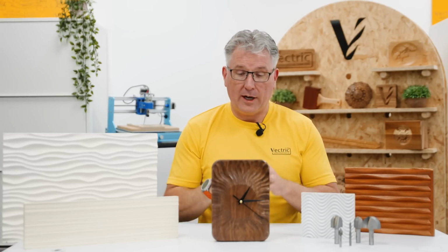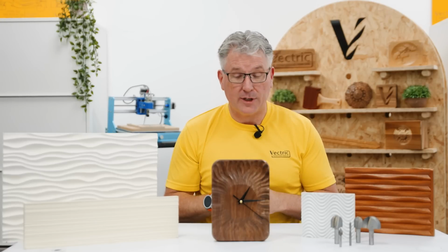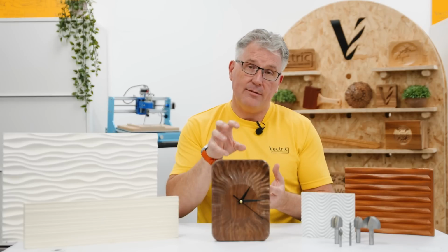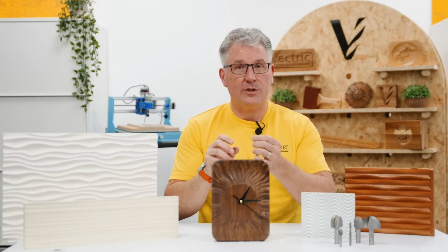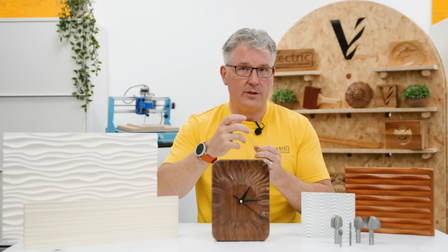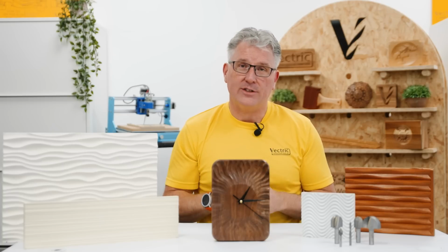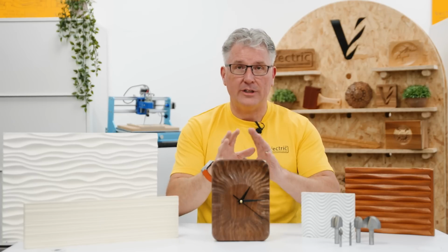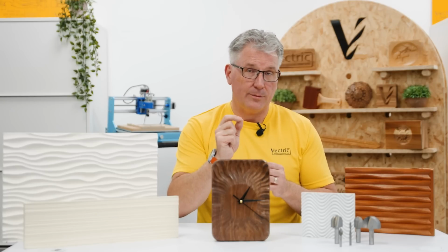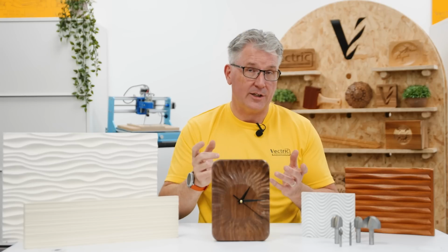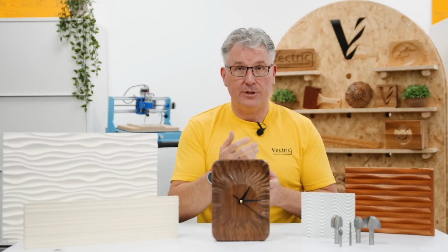Now, I did only one other thing different about this file, and I did change it in the file that you're going to get, is I didn't make the pocket for the mechanism quite deep enough. So there was a little bit too much wood, so I couldn't use the little nut that you get with the mechanism to hold it in place. I don't think it's a big deal, but if that's an issue for you, then just make sure all your depths are set up appropriately. And a top tip, and it's really important to remember this, if you're going to use the toolpaths that I created with that big ball nose, make sure you check those feeds and speeds and make sure they're safe and appropriate for your machine.